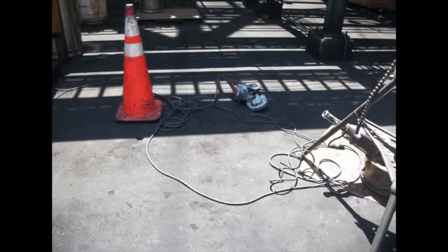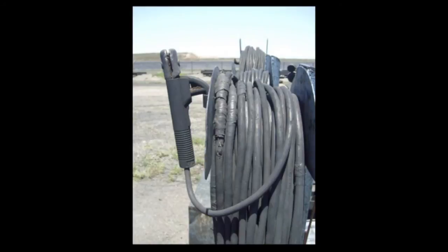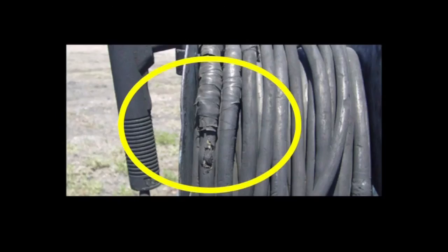The most common type of electrical equipment you'll see in your plant is the standard electrical cord, and the easiest way to injure yourself is to use a damaged one. If you encounter an extension cord, welding lead, or any other electrical cable with cracked insulation, exposed wiring, or a broken plug, report it to your supervisor immediately. It must be properly repaired or removed from service. Electrical tape is not an adequate solution.